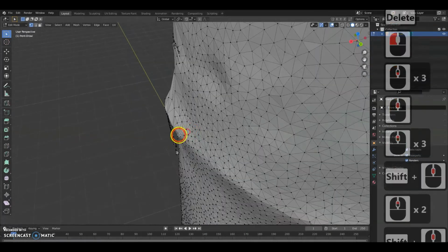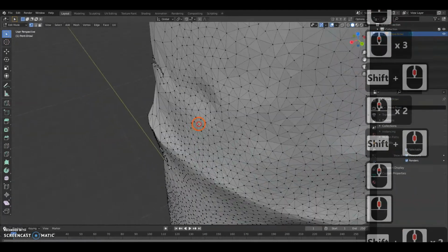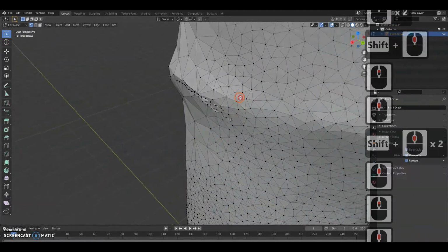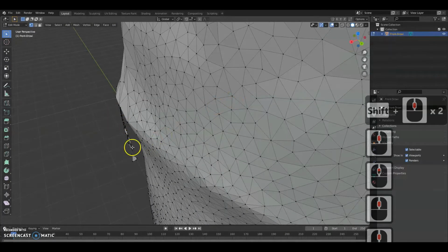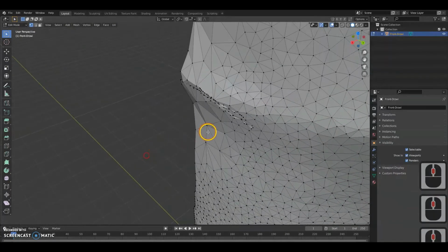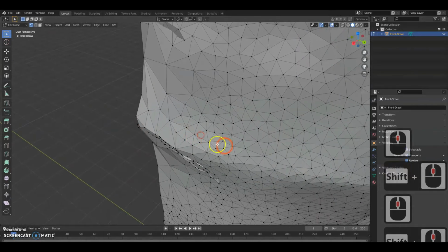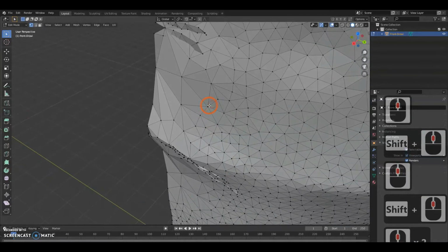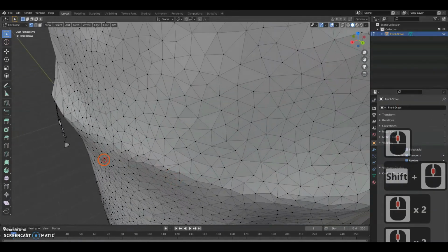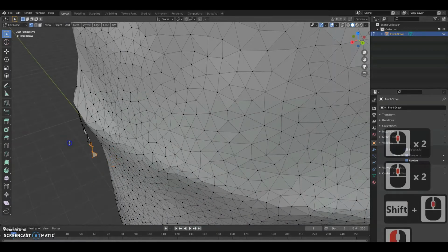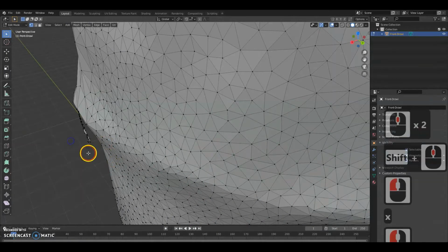And I noticed a few other geometry things in this object, like for instance these weird strings that come off. You don't want these in there. It'll cause really weird issues when you go and try to solidify it and basically give it the depth. So what you can do is just grab all of that and X for delete vertices.